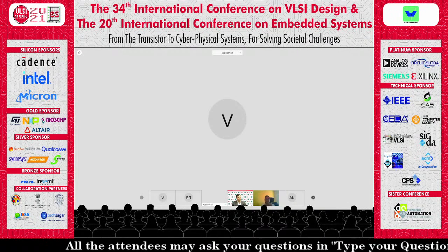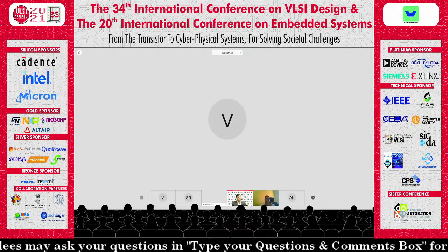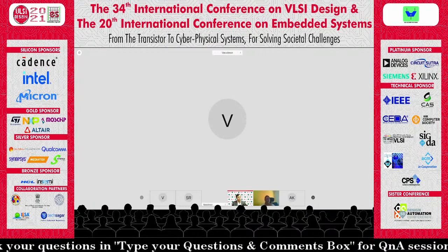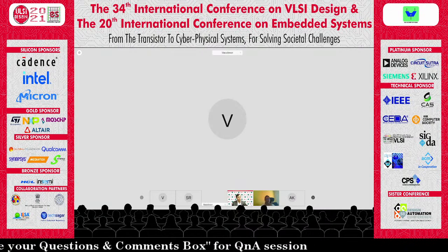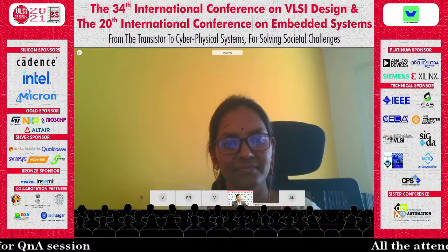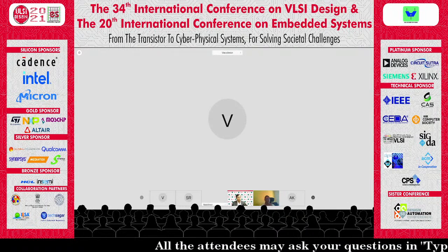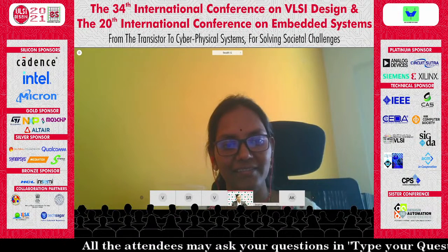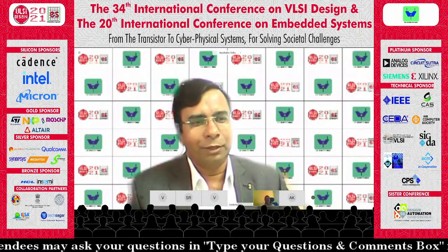That is what we need in this approach, for restoring or replacing the top blocks. So we do the logic simulation for the top blocks, and we replace the state of these top blocks using the contents of the observable locations that we got from the logic simulation. So that's a high-level method. Of course, accuracy is lesser, but we get the observable states. The detail of jargon is not given in the paper. Otherwise, you would have a lot of state space simulations for that.